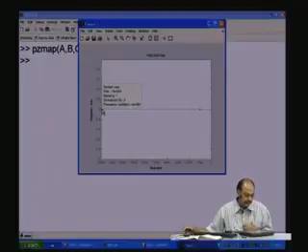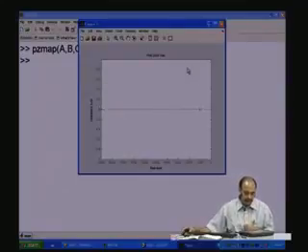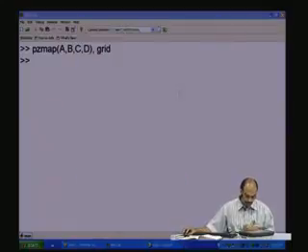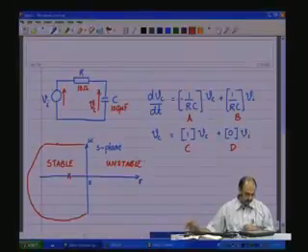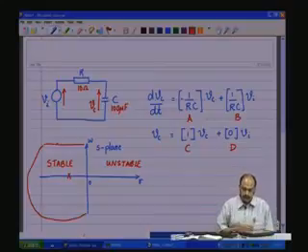So, you can position the pole accordingly on the pole-zero plane, and then get back what should be the R and C values such that you get this pole condition, and thereby you can design your circuits. So, this is an example that I showed you, that is the RC circuit.